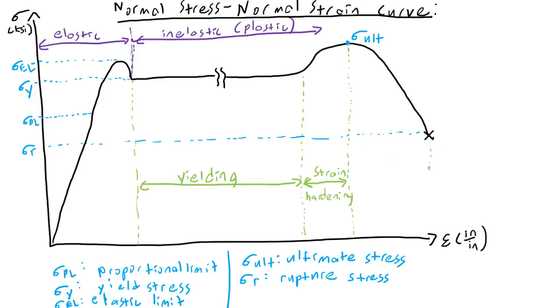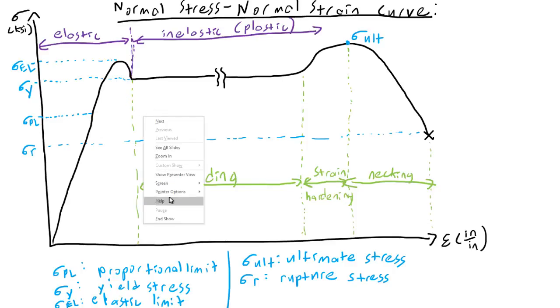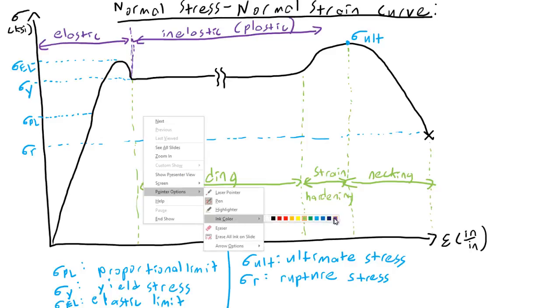And then here, finally, we have the final region where the material is just giving up altogether. This is where the material is rapidly thinning, which happens relatively quickly. This is the necking region, where your sample is rapidly thinning before it just snaps altogether, like a piece of silly putty breaking in two. Okay, so I will define some more of these a bit later on the next slide. Now, I do need to define something, so I need to list some other things on here, sorry.